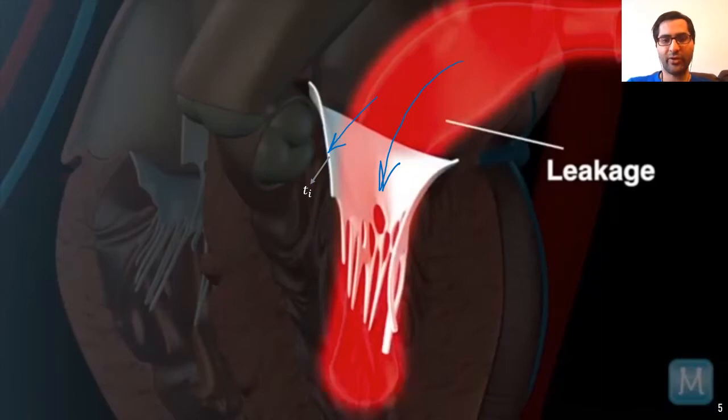The traction is defined at each point based on the normal vector, which is the vector normal to the surface at that point. We show it by N. And the traction itself has two components. One tangent component, parallel to the surface at a point, and one normal component, normal to the surface at a point.